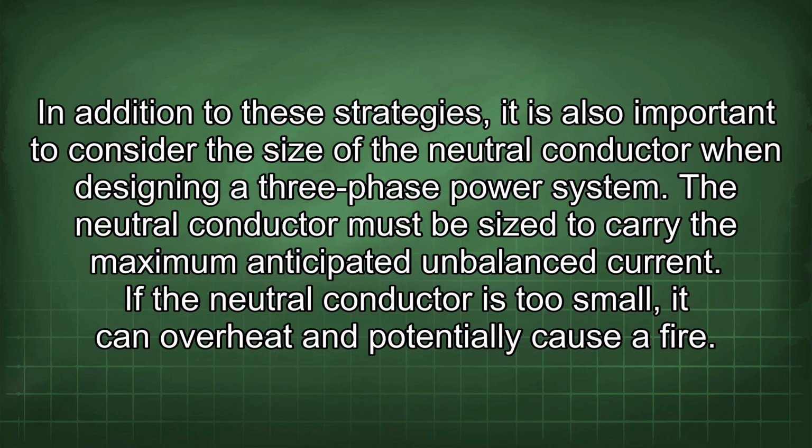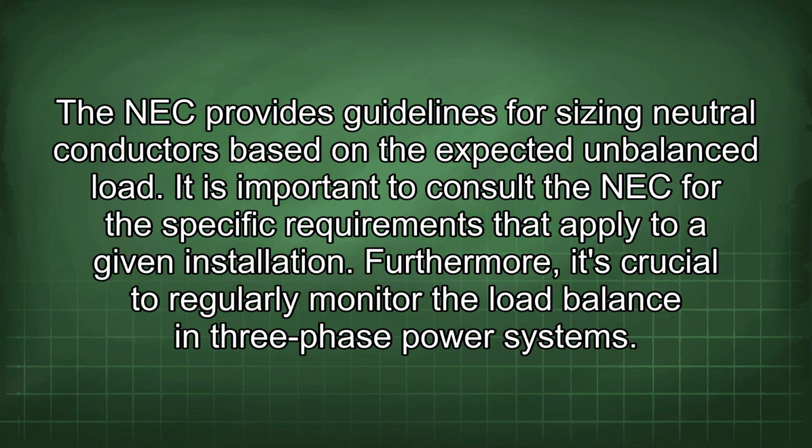In addition to these strategies, it is also important to consider the size of the neutral conductor when designing a three-phase power system. The neutral conductor must be sized to carry the maximum anticipated unbalanced current. If the neutral conductor is too small, it can overheat and potentially cause a fire. The NEC provides guidelines for sizing neutral conductors based on the expected unbalanced load. It is important to consult the NEC for the specific requirements that apply to a given installation.